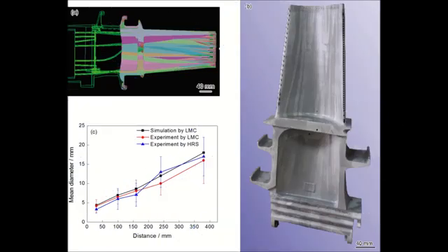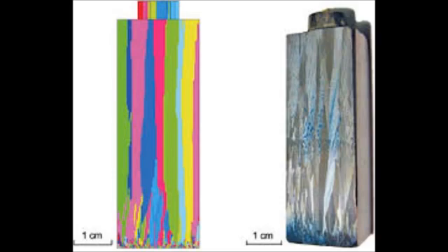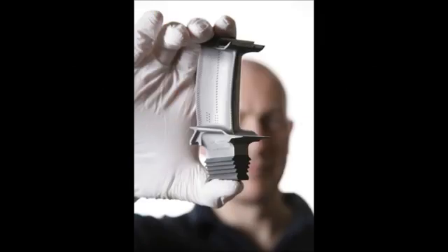Due to these failures, turbine blades began being manufactured with DS. DS arranges the crystals in layers, eliminating some of the grain boundaries in the tensile direction, or the vertical direction, but not in the horizontal direction, improving the thermal fatigue, but not to the extent needed. However, SC took it one step further.